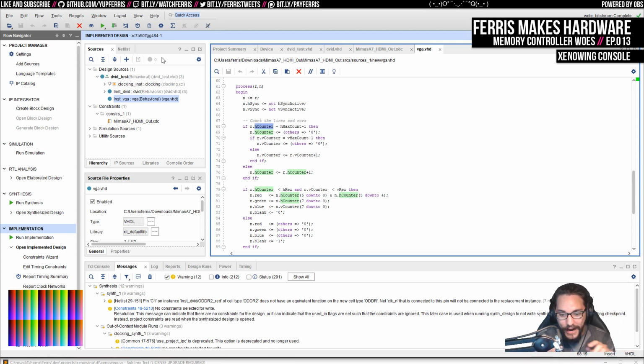Yeah, those resets get routed, as we saw from the simple LED thing that I had, where I had the reset and it was kind of fanned out. That's using routing resources that maybe we don't need. So I would still like to support a reset for the design, if nothing else just so that I can push the button to reset, which I think is nice.